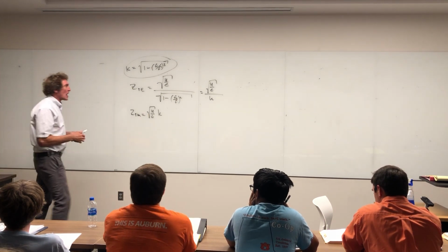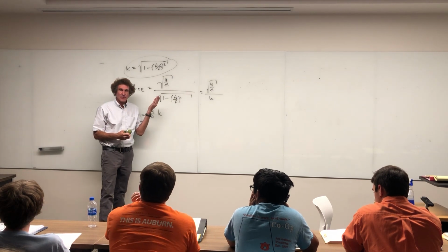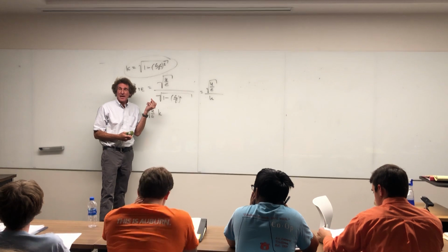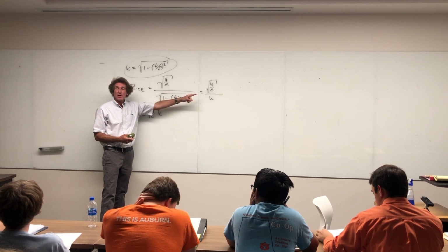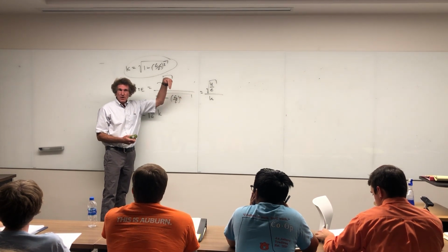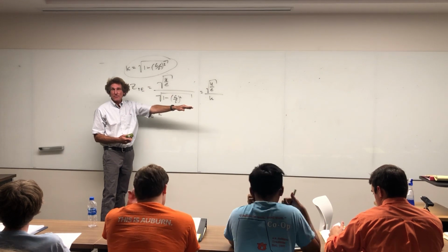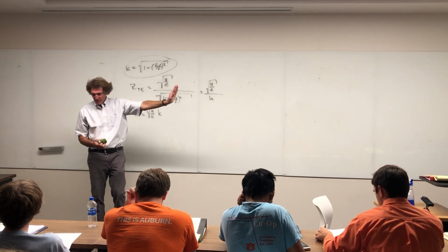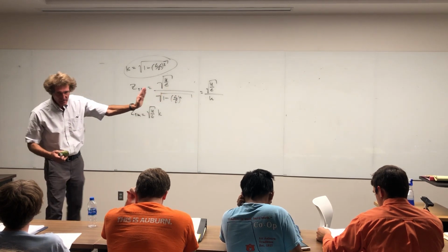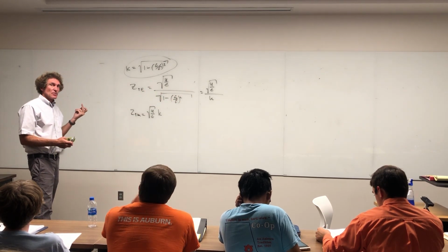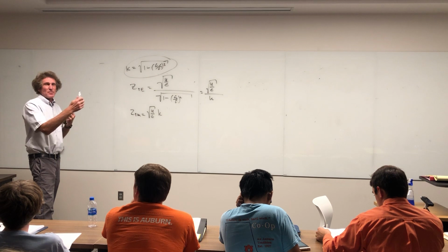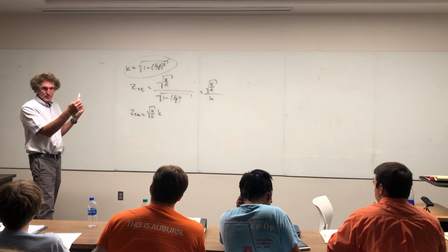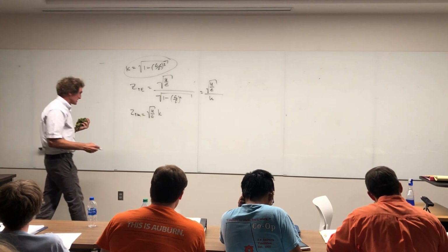But if you try operating really close to the cutoff frequency, maybe 1% greater than that, then this impedance gets very large, all right? So you want to operate away from the cutoff frequency, but not into the next cutoff frequency's range, because then you get two modes. So you want to make sure you're between the first cutoff and the second cutoff, probably 60% above the first cutoff will do, and that'll be fine. Follow me? This is just some advice.